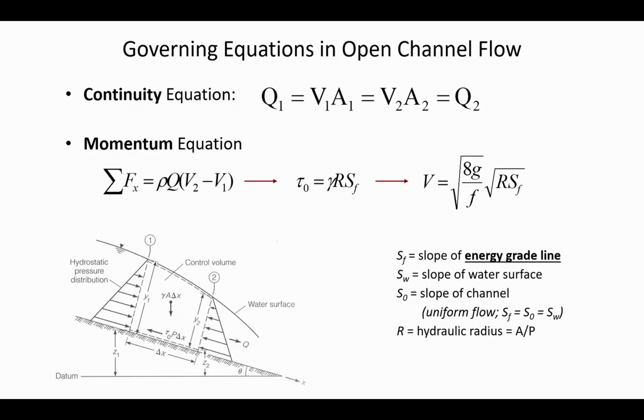So if this is non-uniform but steady, that means that the depth is constant over time, then A1 V1 has to equal A2 V2. So even though maybe the velocity is faster at 2, the flow rate is the same because the depth is less.